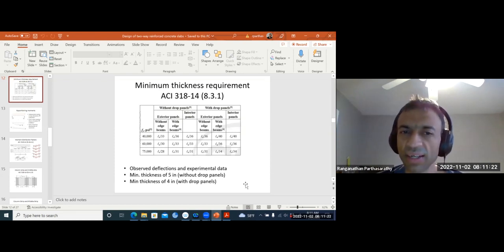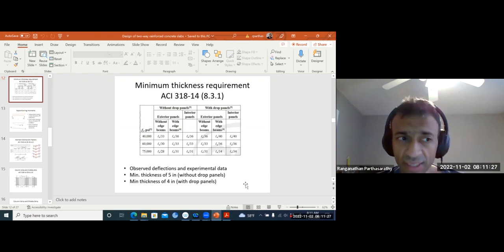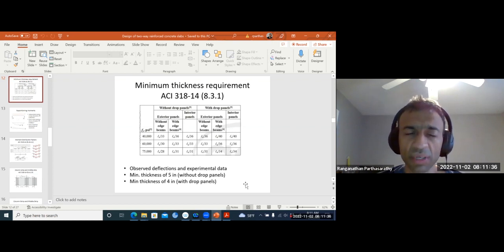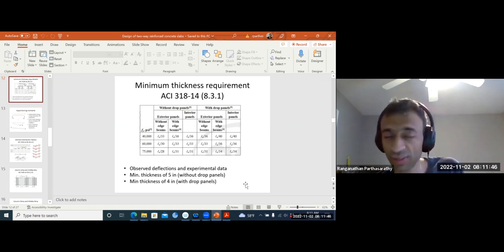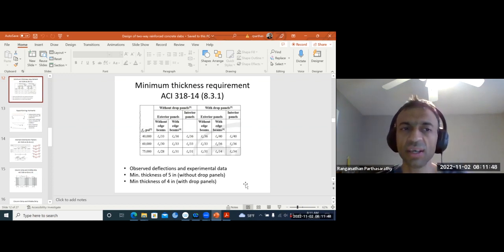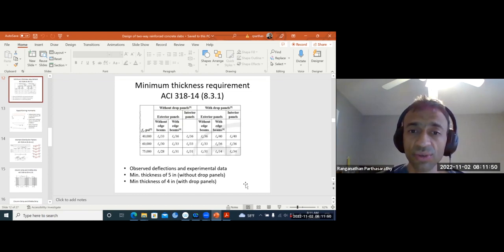That's absolutely right, to make sure that the deflection requirements, as you're saying, they depend also on the use of the building. Like if there is some very sensitive equipment there, maybe they want under quarter inch or something. So then you need to make sure of that. You need to adjust your design accordingly. Maybe you may even need to go for a pre-stressed slab where you will have very little deflection.